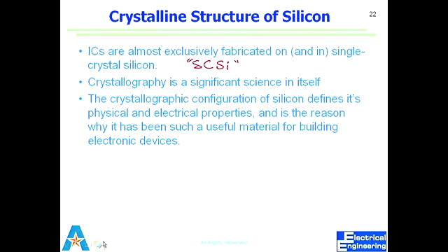So you could actually make lines with heavily doped polysilicon, and they will act like conductors. And now I can do heavy thermal processes. You could put them in your 800-degree furnace. And 800, 1000, 1100, whatever. It will get oxidized, right? But not at the same rate as single crystalline silicon, because single crystalline silicon has a certain density of atoms available for oxidation, reaction with oxygen, and polysilicon has an entirely different one.